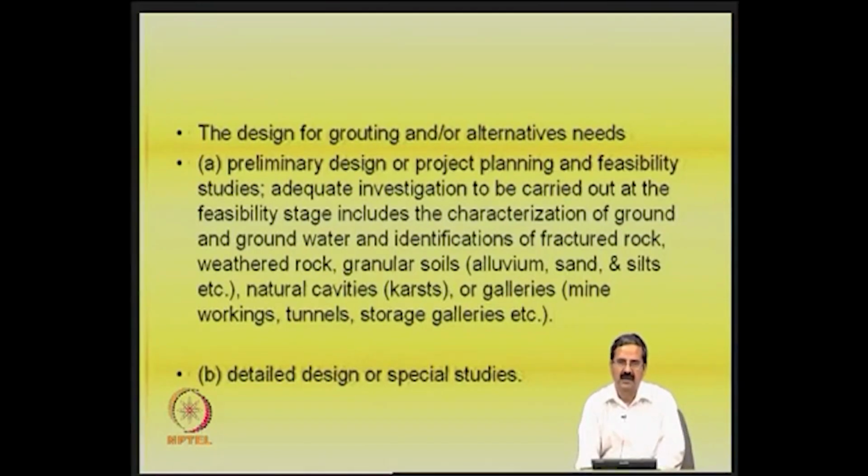So, for example, you are trying to characterize the area in a rocky slope, you would like to see whether the slope is stable. And whether it has any underground water resources, perched water or whatever. So, one should be able to understand what exactly is the type of rock or soil, then understand what the water table levels are, and identify the fractured rock. If fractured rock exists, it leads to stability problems.